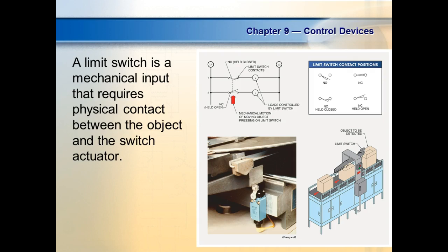We have them on elevator doors. So how does the elevator door know when the door is open and the door is closed? It's got a what? It's got a limit switch that actually hits that switch up there to let it know. So to know it's either closed, it's up against this limit, or it's fully open, it's up against that limit, right? So we had motors that would run forward and reverse, and it would hit it when it would try to move them a certain direction. So these became known as limit switches, even though they have a lot of functions.